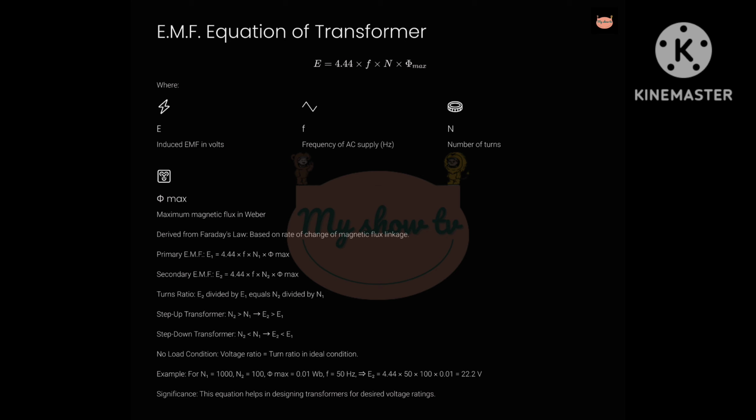This equation is derived from Faraday's law, which relates the rate of change of flux to induced voltage. 3. In a transformer, primary e.m.f. E1 equals 4.44 times f times N1 times phi max. Secondary e.m.f. E2 equals 4.44 times f times N2 times phi max. 4. The turns ratio defines how voltage is transformed. E2/E1 equals N2/N1. If N2 greater than N1, step up. If N2 less than N1, step down.